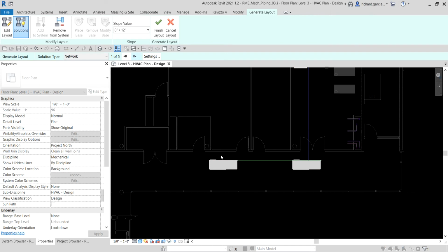If you select system components to create a pipe layout and the selected system components are already assigned to more than one system because they have multiple system connectors, then the select a system dialog displays. You select a system in the dialog to view it in the drawing, and then you just need to select OK.